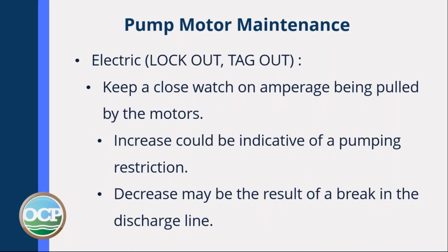You want to keep a close watch on amperages being pulled by the motors. An increase could be indicative of a pumping restriction or clog. A decrease may be a result of a break in the discharge line.